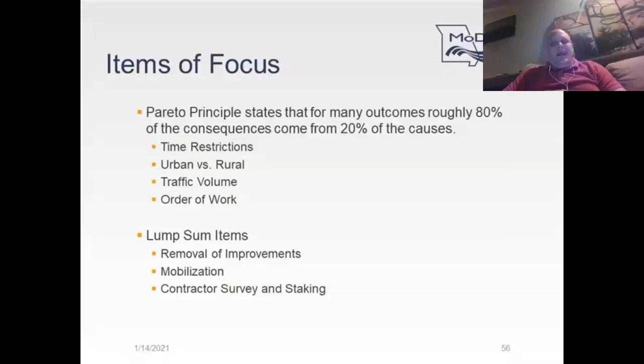Still using your bidtabs.net, you will run a pay item search and refine your quantities and area to come up with a cost. The report will have averages for the parameters that are established. There are prices for above and below that price. There's low and high bids that we received on those pay items, and it provides an average.